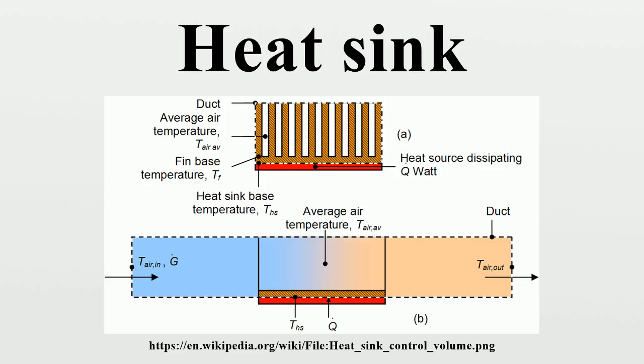Heat transfer principle. A heat sink transfers thermal energy from a higher temperature device to a lower temperature fluid medium. The fluid medium is frequently air, but can also be water, refrigerants or oil. If the fluid medium is water, the heat sink is frequently called a cold plate.